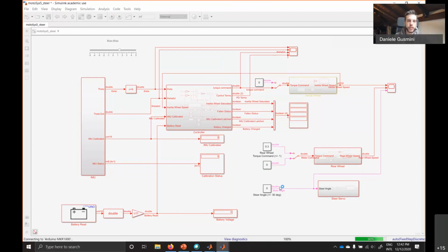You are still testing it, and maybe you need clear feedback from the sensors and the variables inside your system. Using the external mode, you are running the code on your Arduino as if Arduino were completely separated from Simulink, but keeping a link between Simulink and Arduino. We can see through the serial communication the quantities and the signals inside the system.